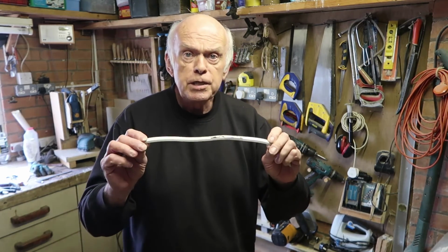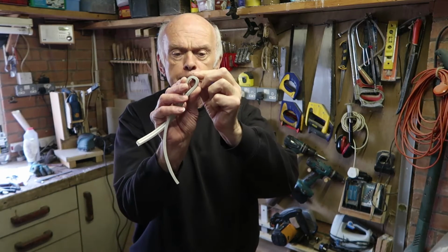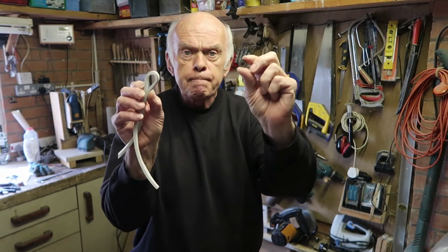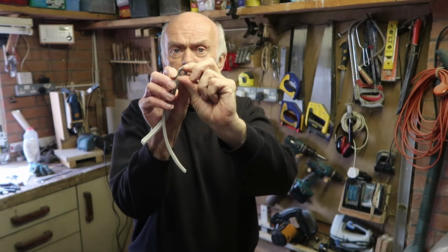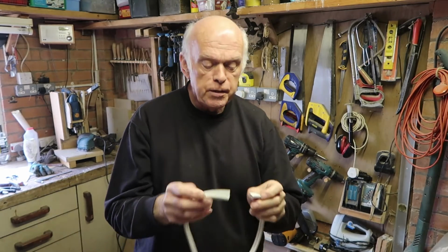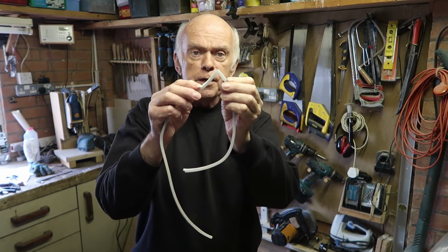You can make a light from pretty much any photo. The only limit with a continuous LED strip is that the minimum internal or external radius is about 6mm for shallow bends or 8mm for full 180-degree bends. It is possible to make a sharper corner by cutting the light, but I think this could possibly detract from the appearance.